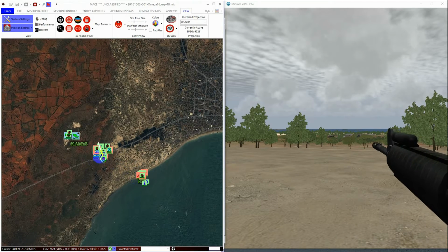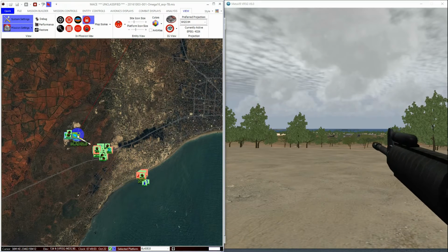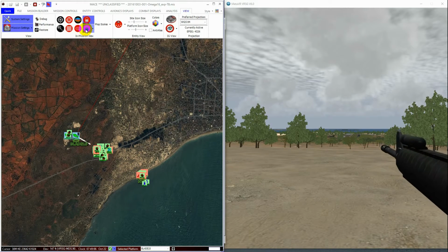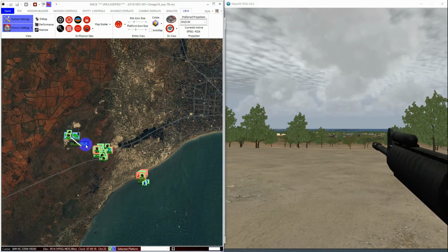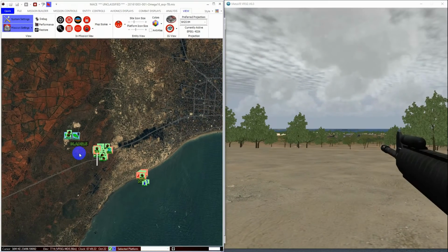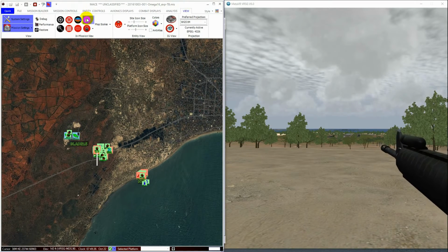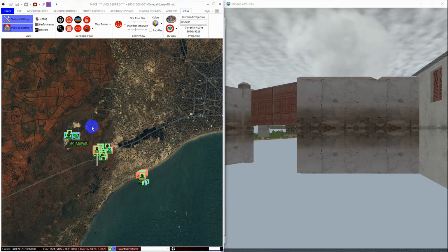The same applies to the bottom lock. If I select a platform and click bottom lock, then the camera is attached to the platform, which is selected in the mission area, and when I click on other platforms, the camera view remains in place. You can tell that the bottom lock has been applied because there is a second black dot that will appear below the top lock. You can bottom lock and top lock to different platforms, and both will have the black dots.